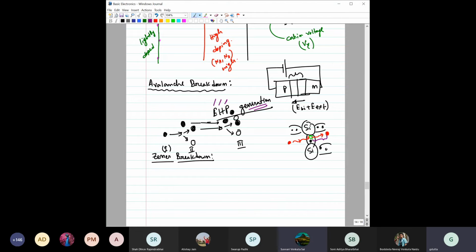Sir, yes. And also there will be more electron hole pair generation due to the electric field, right? Not only a single pair will be generated. Yes, that is actually how the avalanche process works, right? One electron generating one electron, so still this electron is there, and they can again collide and generate another two. This generated electron can create some more. So this is happening because of the electric field as well. Even though there are no collisions, due to the electric field itself they can all form electron hole pairs, right? Due to this electric field, yes.